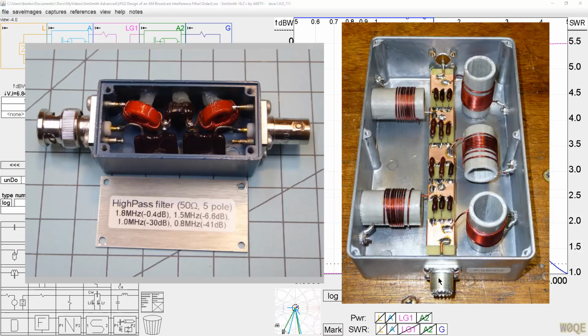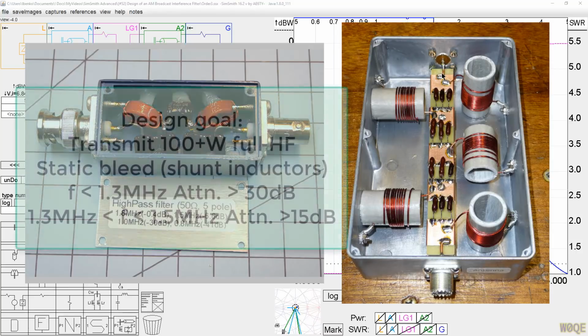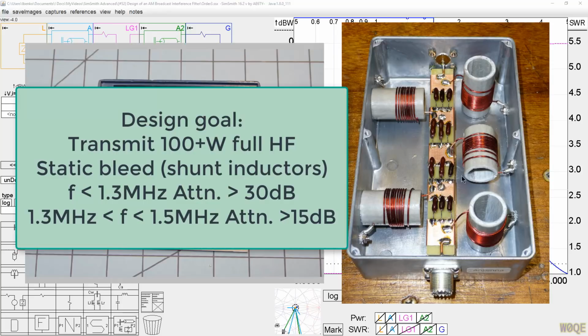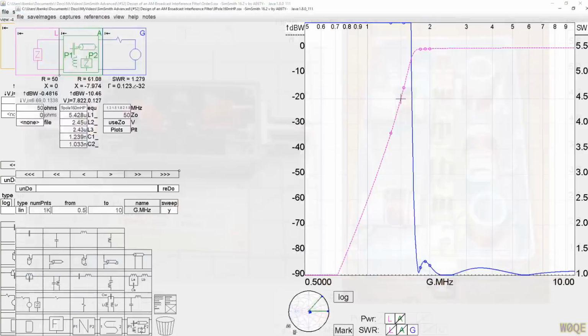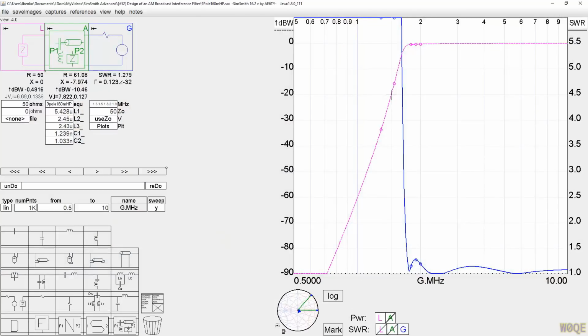And this filter you can transmit through at 100 watt level. It's a 9-pole filter. The capacitors are parallel to give me the right values. And this big wide strip in here was to maintain better SWR. But this filter was to stay in all the way from 160 through 10 meters and have low SWR at the higher bands, so you didn't need to switch it out of the circuit. And let's look at that circuit right now. And there it is.